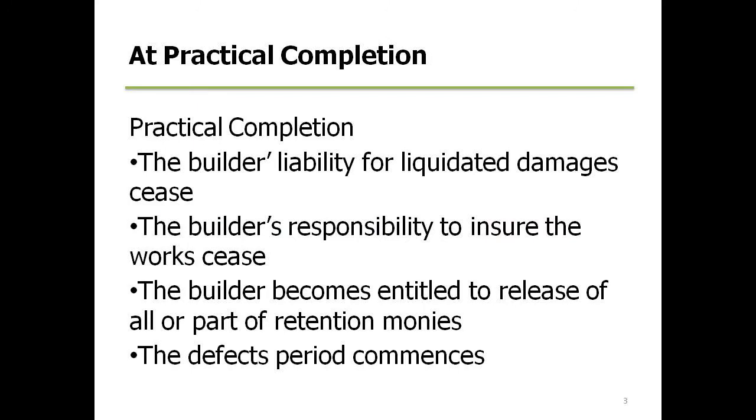So although there's a long list of things that need to be considered at practical completion, it's a time when the builder's liability for liquidated damages ceases. So the threat of him finishing late and that costing him money is over with. At practical completion he also doesn't need to insure the works anymore, and the release of part of the retentions becomes available, and this is when the defects period begins as well.